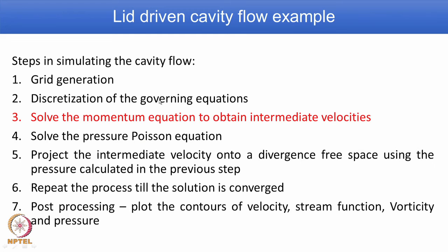In the u momentum equation, we had the diffusion term explained in the last module. In this module, we will focus further on the u momentum equation, considering the convection term, and then extend this procedure to the next momentum equation, that is the v momentum equation.